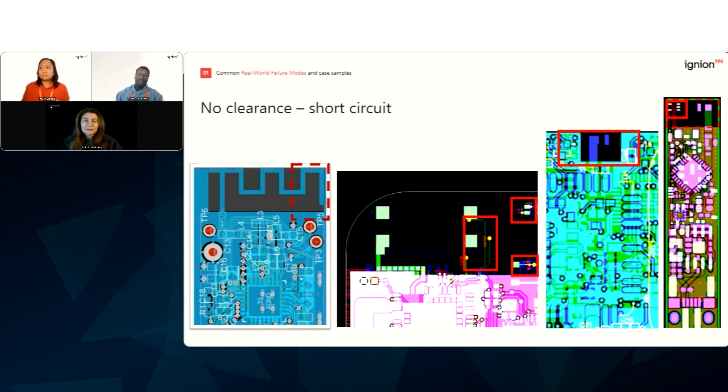And the rest of the pictures are just pretty obvious. There's not enough room for the antenna to breathe. There are rules regarding what you do for keep out areas and so forth. And typically in any data sheet, we would stipulate those for a reason, because we've done some studies to understand the impact of proper clearances, et cetera. The one on the left, that's a blatant mistake, obviously, because in the design of this meandered PIFA, the long arm is shorted to the ground plane, right?